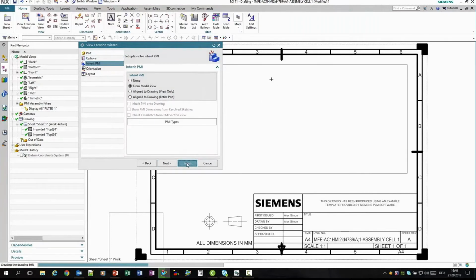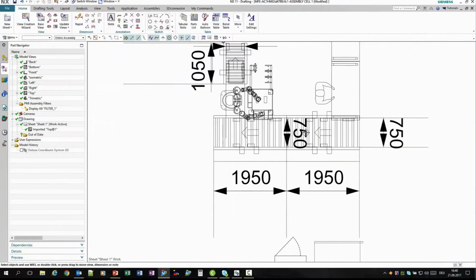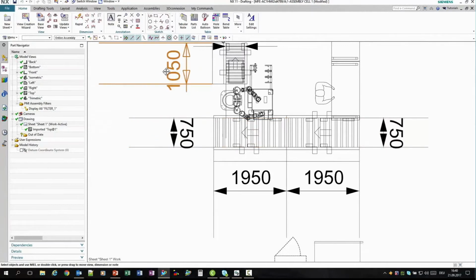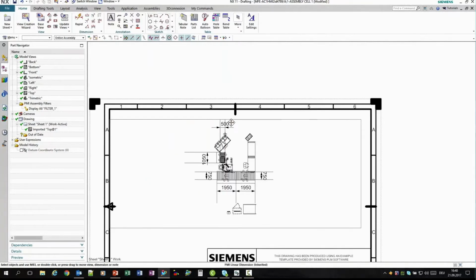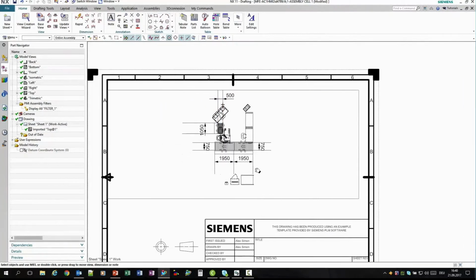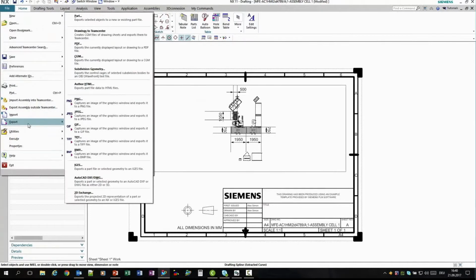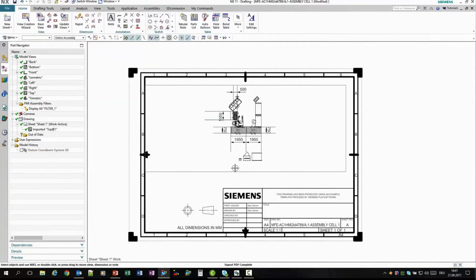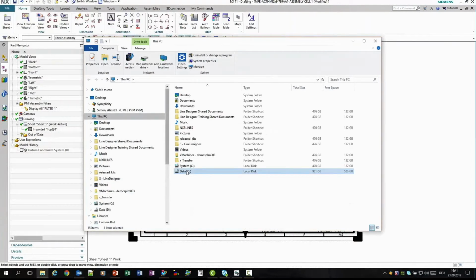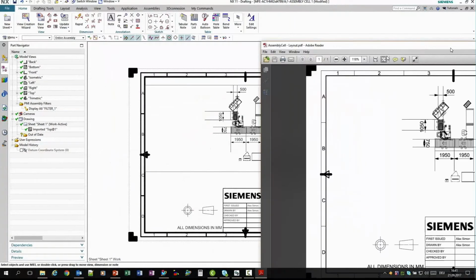Also, I want to inherit PMI, the product manufacturing information. I customize the length and the width of these. So when I purchase these components, I need to send information to the supplier so they make the right size one for me. Just by hitting a button, anything that's not standard off the shelf and is customized or semi-custom, it documents that information so I can make sure I get the right products in the right place when I do install on the plant floor, and the purchasing team knows exactly what to order. They don't have to go look at the 3D CAD, I can document it in a drawing. So you can see these drawings are fairly simple to create. There's not too much difficulty there.